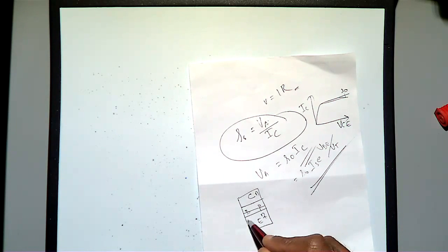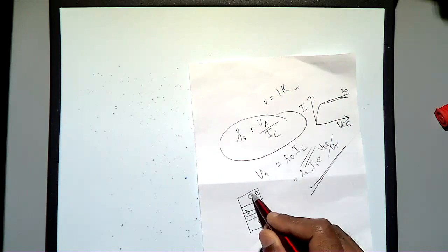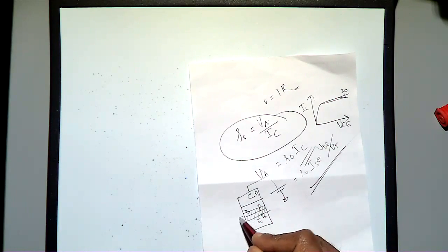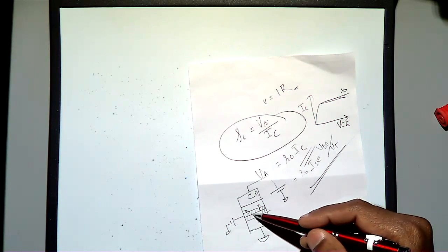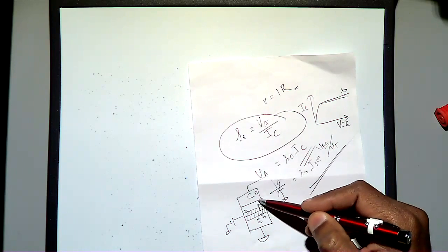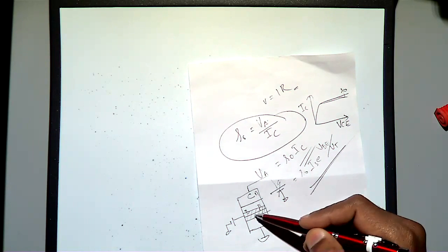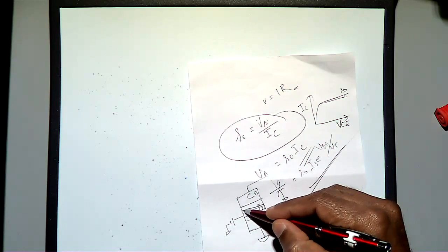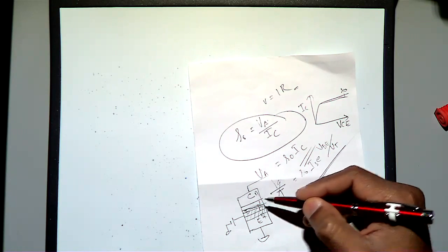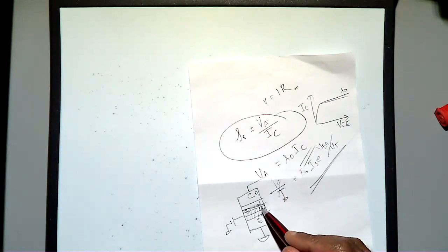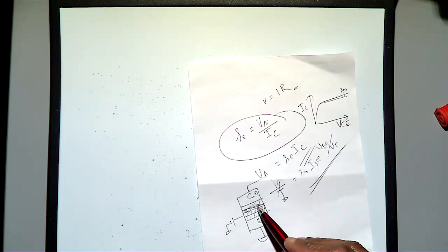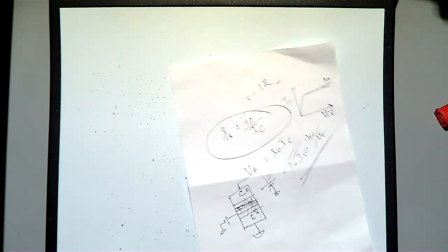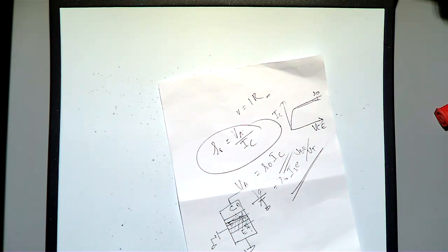Here you are getting the junction, and when you apply more voltage here, this is your VBE. If you recall, why are we getting the early effect? When you increase this voltage, this width decreases, because the reverse bias will increase from here to here. You get a smaller width, and the electrons coming here will recombine with only a smaller number of holes. That's the reason your collector current is increasing, which we already discussed. But the problem is we don't know how much it is increasing. We can't see it, it is inside the semiconductor. So actually you don't have the control.